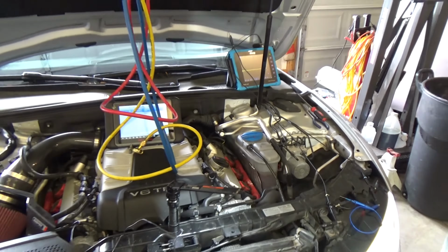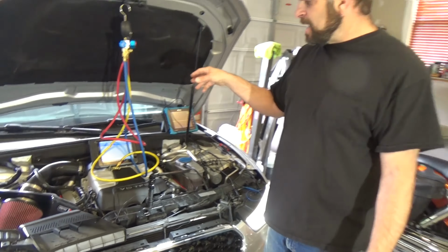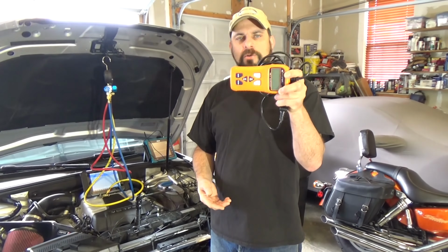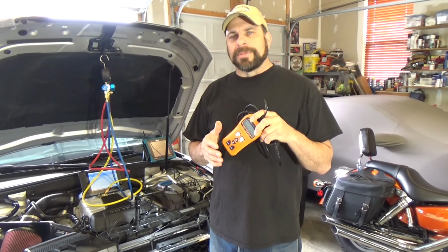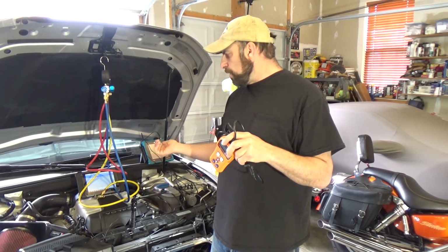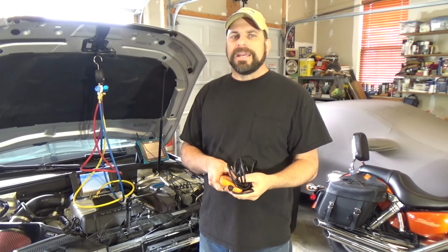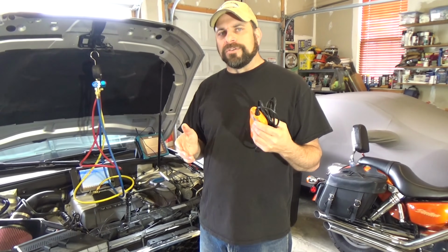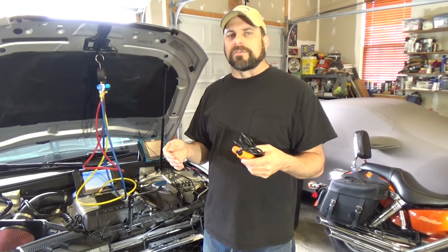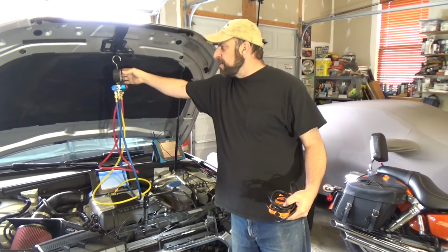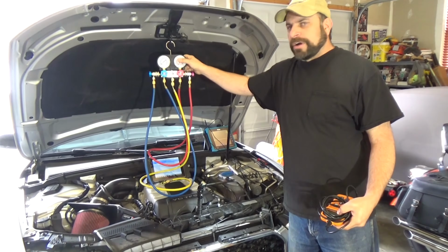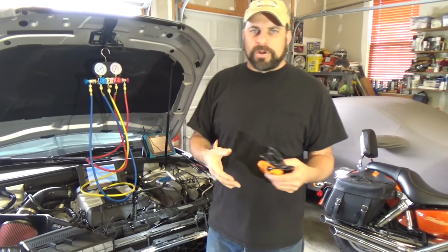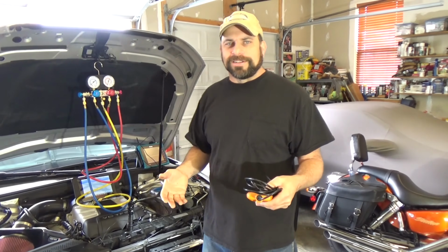Now most people aren't going to have this equipment. They may not even have this fancy scan tool that I just showed you. Maybe you have one of these, a smaller code reader, and I'm not saying that all code readers won't pull those codes that I just showed you, but you may not get any trouble codes. So keep that in mind. If you do get those codes, that's great. If you don't have a set of manifold gauges, which is for your air conditioning pressures, your high and your low, it's going to be part swap-a-roo time, basically.